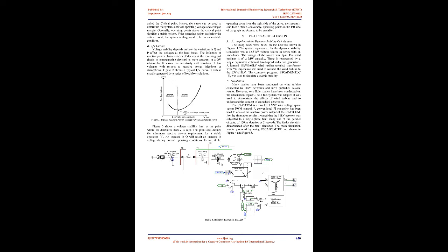A. PV curves. When considering voltage stability, the relationship between transmitted P and receiving end V is of interest. The voltage stability analysis process involves the transfer of P from one region of a system to another, and monitoring the effects to the system voltages, V. This type of analysis is commonly referred to as a PV study. Figure 2 shows a typical PV curve.